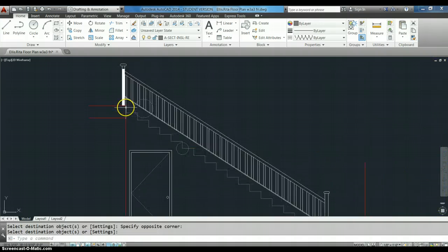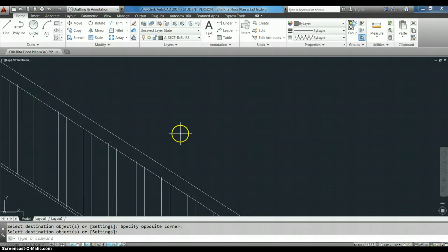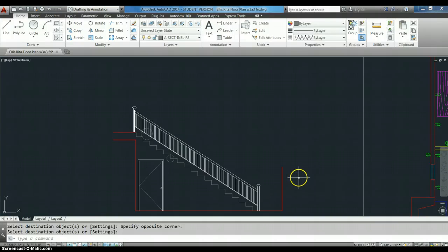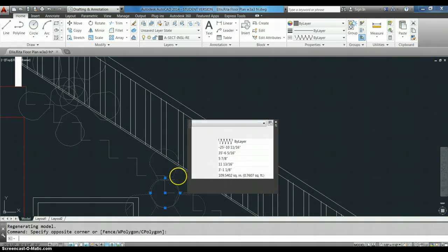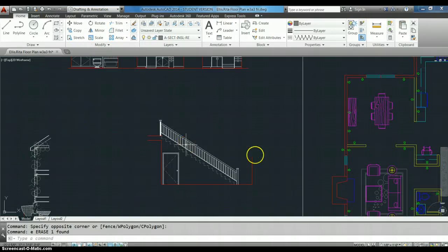That's better. Okay, so do a little cleaning up, really zoom in close so you can really see. And I'm just using my mouse wheel to zoom back and forth. I'm sure you figured that out. Now let's deal with the other weird problem, which is the line type scale issue. So I'm going to just type LTSCALE, again, or 1. Okay, so that's better. Yeah, all these circles I drew, I guess it was on the insulation line type when I did that. So now that's looking better.